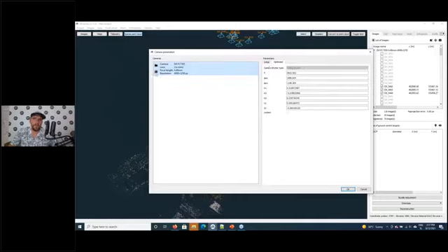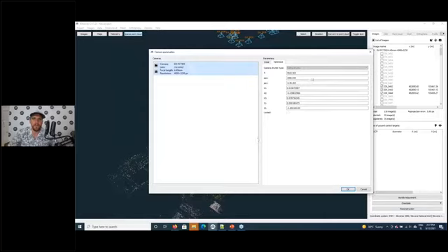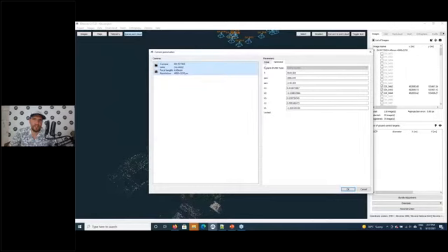So what we will do now, we will save these parameters into an external file, and I'll use, for example, 00, to denote that these are just some initial values. So these parameters, and then we will immediately use the load camera parameters button, and I will load in these 00 camera parameters like that. So now our initial camera parameters are the same as our optimized camera parameters.